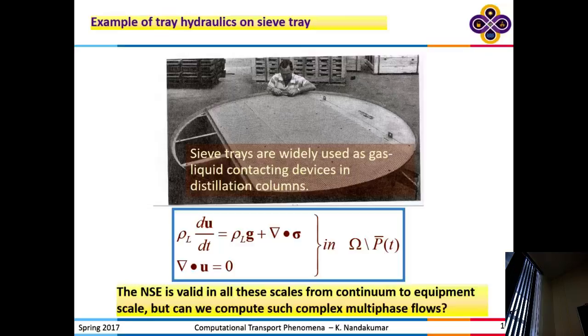That is a momentum conservation equation. This is the mass conservation equation. So it's a combination of both mass and momentum conservation. This is mass times the rate of change of velocity, which is acceleration, equal to the sum of the external forces: gravity is the force, and then the so-called viscous forces, right?